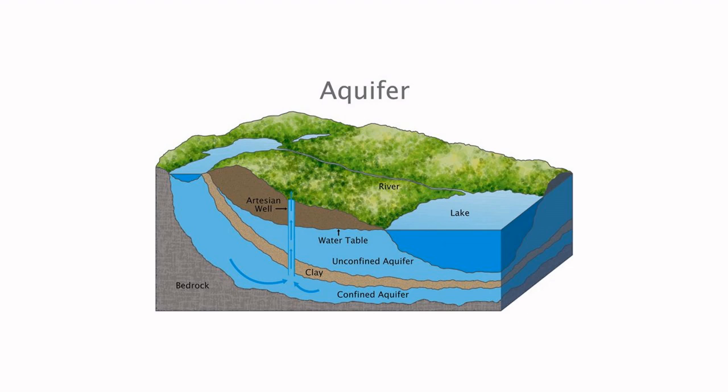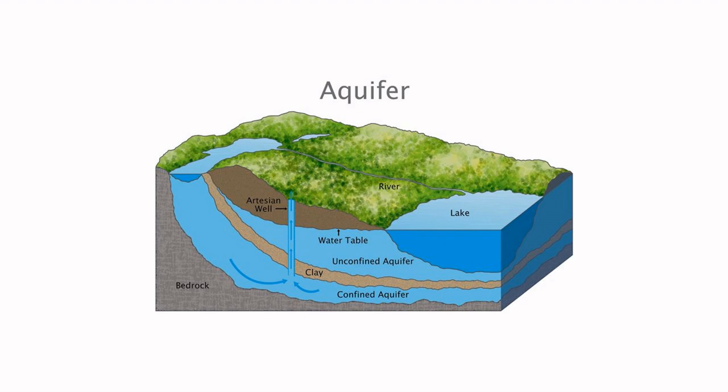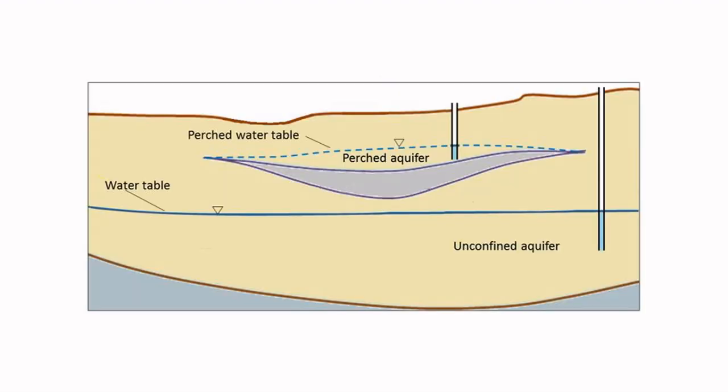If the material in the intermediate zone is isotropic, and if recharge takes place, the moisture content in the intermediate zone will generally range between near saturation and as low as the specific retention of the material. The intermediate zone terminates below the capillary fringe. The transition to the capillary fringe is rather abrupt in coarse-grained sediments, but is very gradual in silts and clay.